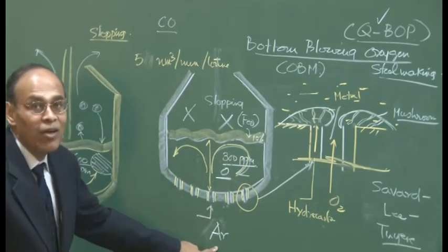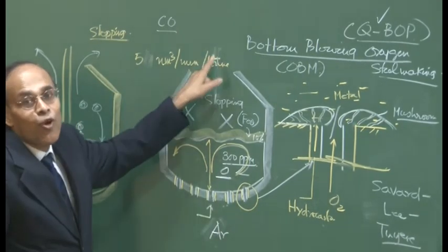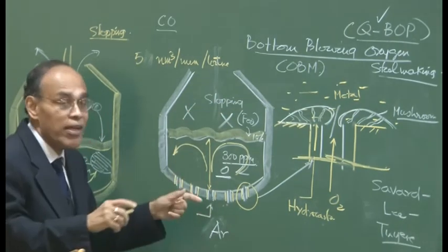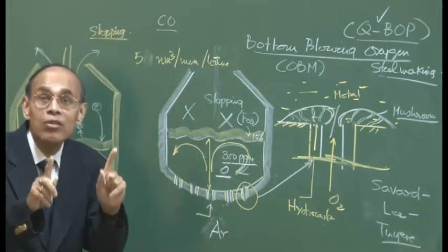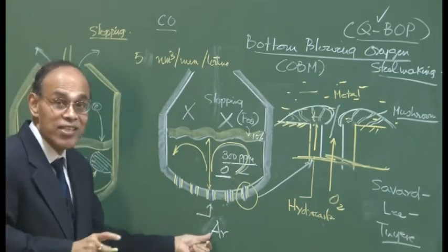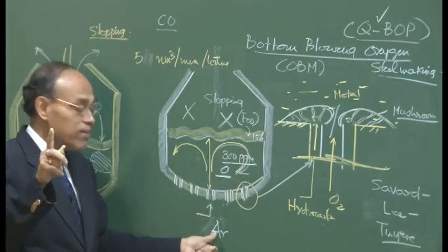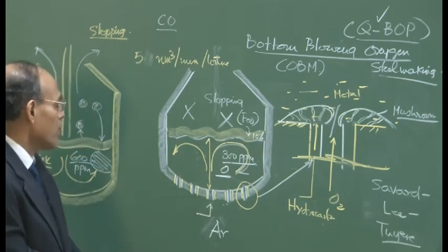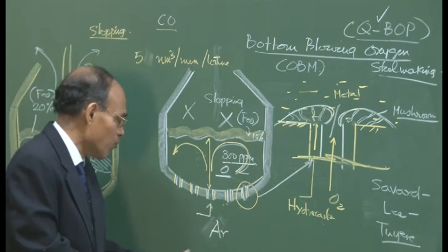How much argon? Only 2 to 3% of the top volume of the gas, a barely small amount, and thereby not through tuyeres but through porous plugs, because it is a small gas injection. I have made the statement that if we want to inject a small gas flow rate, the best thing to do is the porous plug.